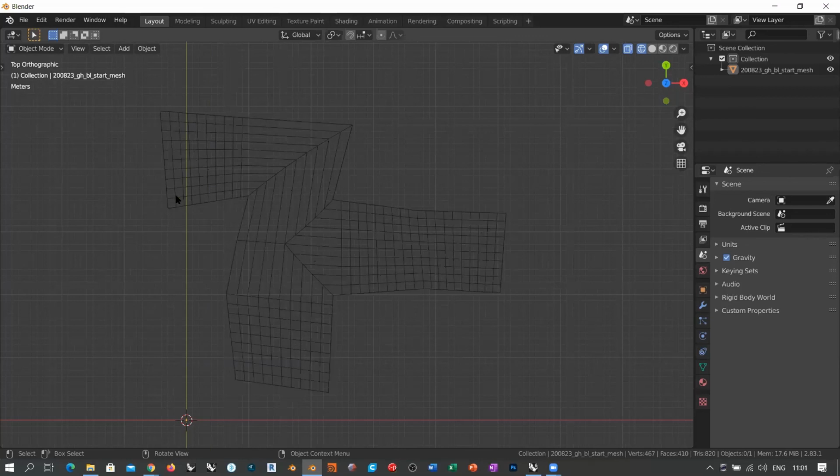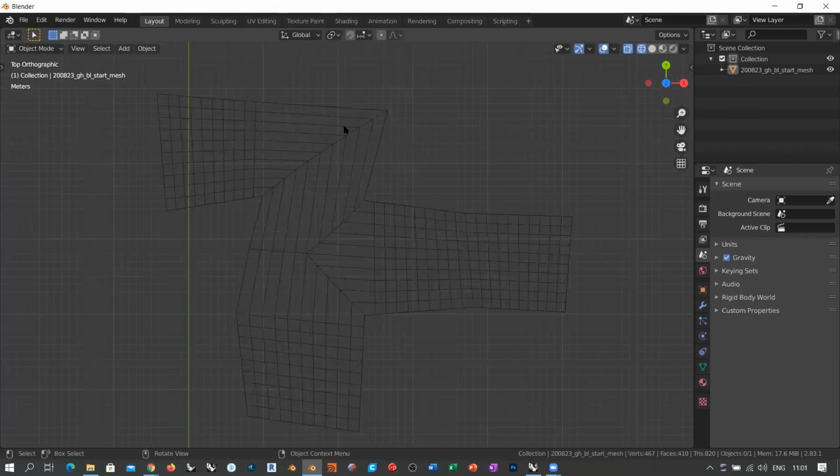And in Kangaroo, this means that you have very large springs and very short springs in different areas. And this means that this area can deform more smoothly, and this is a very low resolution part. So what I would do in this case would be to decrease the resolution of this mesh globally in order to obtain some low resolution aspect.